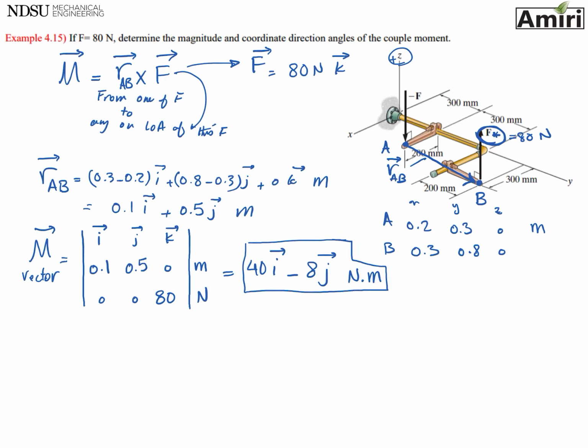So now let's look at a figure, see if that makes sense. So think about these two forces being applied at the steering wheel. The rotation you get is this way. As a result, your moment is going to be in this plane. Okay, it's not parallel to x, not parallel to y. It is just the moment is this way. It's not parallel to x because if you look, force B is at 300 millimeters, the other one is at 200, so it's not exactly straight.